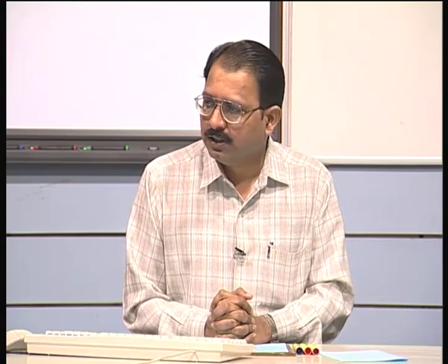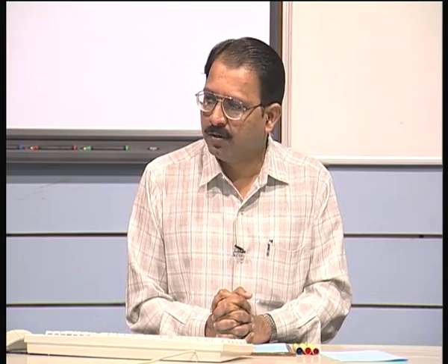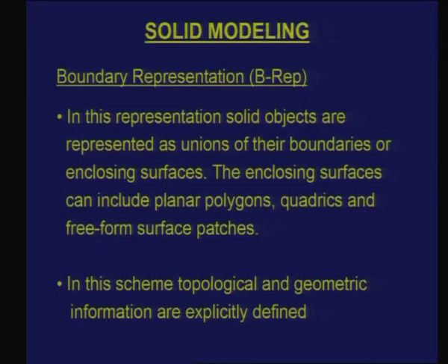Now another very popular representation for modeling solids is what you call a boundary representation. It's more commonly known as BREP. Okay. Now what is done in a representation like BREP is the object is basically represented by the boundaries or the surfaces which are enclosing the boundary of a solid object. So you are not representing the complete interior points explicitly. You say that here are the boundaries.